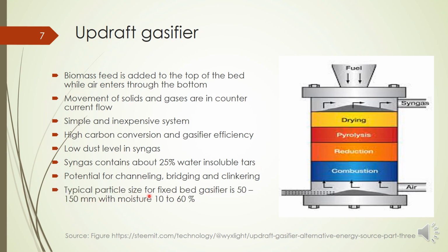And a typical particle size for a fixed bed gasifier is in a high range, some 50 to 150 millimeter. That means up to 1.5 centimeter particle size you can use, with a moisture content of 10 to around 60%. So their particle size is comparatively high compared to other entrained and fluidized bed gasifiers.